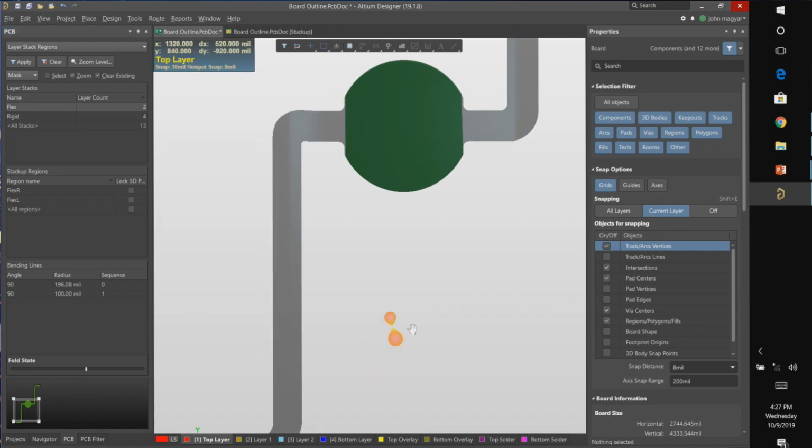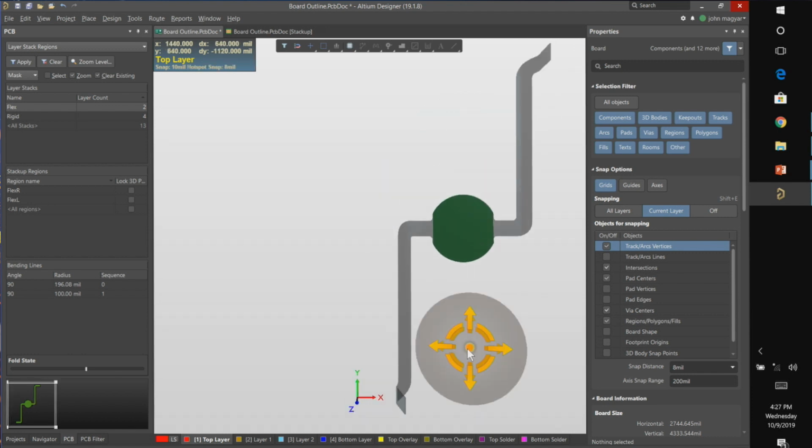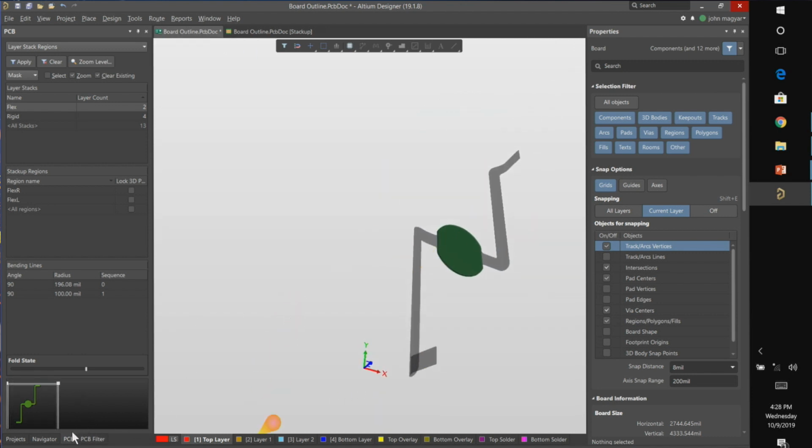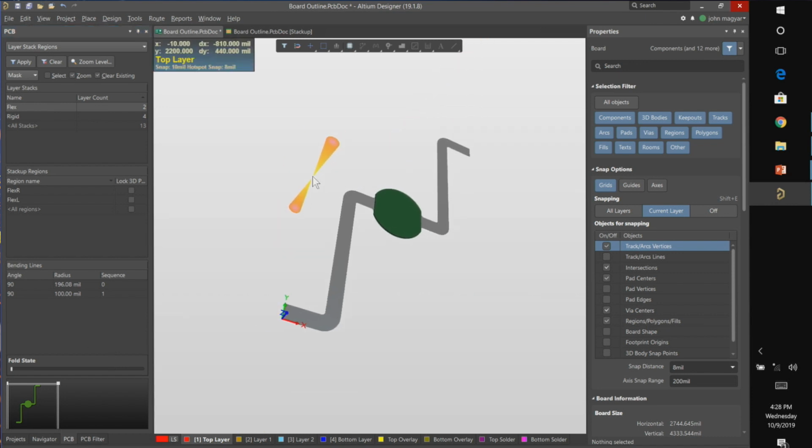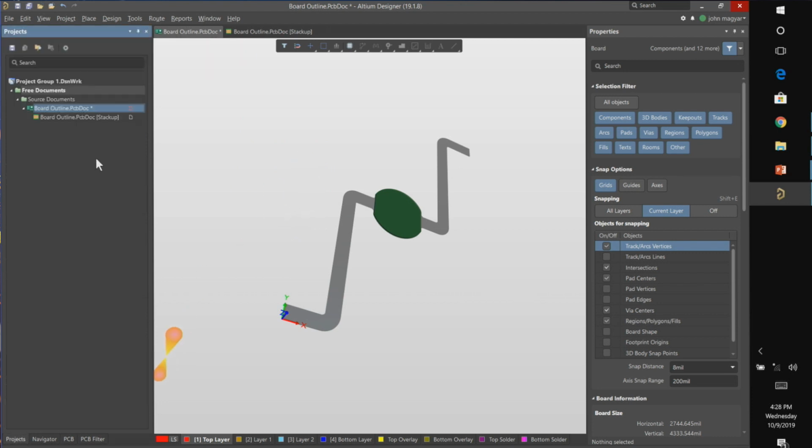And you can look at this from different angles, and it helps much better than working with paper. So you can start to get your creation to do what it wants. We have a much more complicated set of bending lines. Too many to do in one sequence, but I'll just refer to this in the next design. So that's pretty much the bulk of getting to a rigid flex design. There can be any number of rigid sections. There's no limitation.